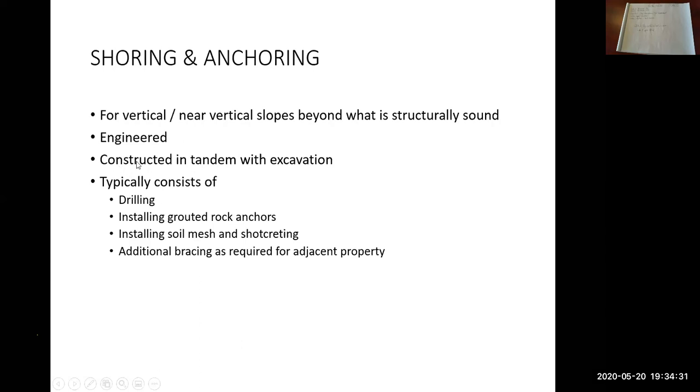So these specific type of systems, the shotcrete with the soil anchors, are built at the same time with the excavation. What I mean by that is you don't do all the shoring first and then excavate. You do a little bit of excavation, a little bit of shoring, a little bit of excavation, a little bit of shoring. So it's very slow, very costly, but it works well. Again, we'll get into an example after the PowerPoint of what a system like that would look like as far as estimating.